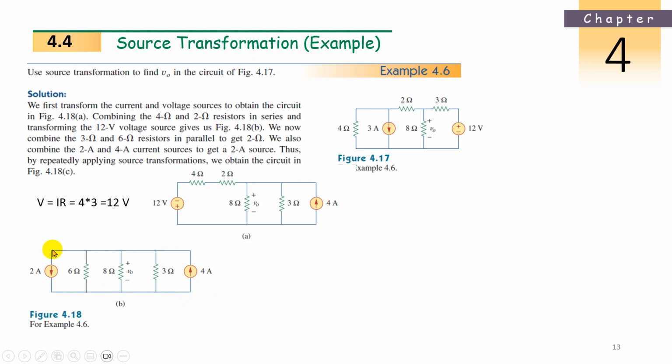Okay. Now this is completely all in one node. This also down is another node. 2 nodes are there. So how many currents are entering with this current source? In this node, current is leaving 2 amperes. Current is entering 4 amperes, right? So effective current will be 2 amperes. So I can rearrange this 4 and 2 amperes current with one current source of 2 amperes, because 4 is entering, 2 is leaving. 4 minus 2, how much?